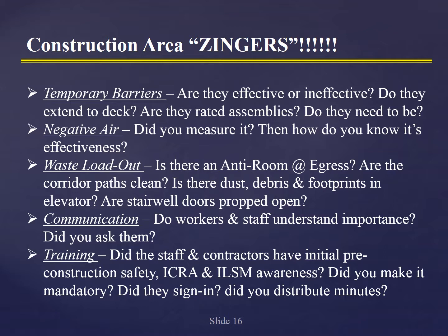Waste load is also another major situation. Do we have a plan for egress? Is it going to go out the window, or is it going to go out through the building? If it goes out through the building, are the corridor paths clean? Is there dust, debris, and footprints in the elevator? Are stairwell doors propped open? Is it covered? Does it need to be sprayed and wetted down? There's all kinds of considerations when it comes to waste.